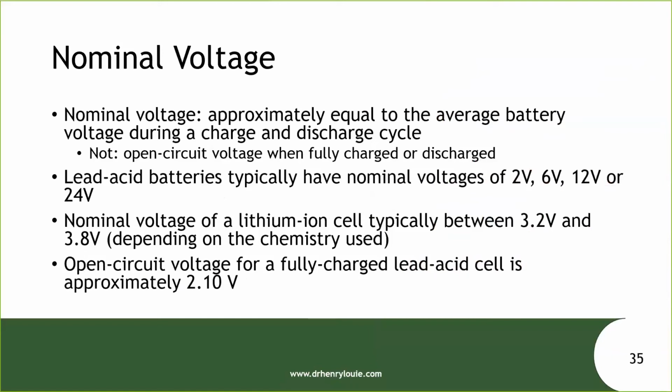You've probably heard of the most famous battery out there, the 12-volt lead acid battery. Well, a 12-volt lead acid battery, when fully charged, will not have a voltage of 12 volts. And when it's discharged, it will not have a voltage of 12 volts. It'll be much lower. So these are just nominal values.